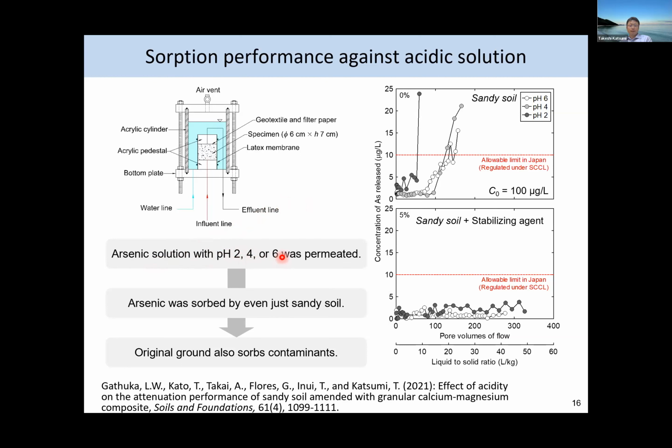And yes, we predicted that pH 2 should have rather severe conditions if we have only a sandy soil as the attenuation layer. But if we have a stabilizing agent to enhance the attenuation and sorption performance, you see in all the cases they satisfy the allowable regulatory limits in this country.